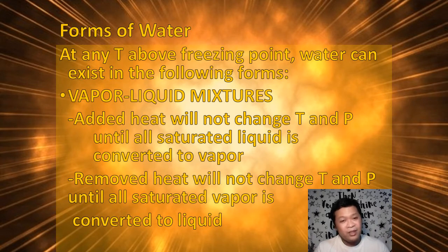So, dahil yung ibang lumang ref nag-on off lang, or yung iba naman, they run at let's say half the rated capacity, kaya kinukuha natin yung average na let's say over a day. Kasi yun naman ang mahalagang bottom line sa atin: how much are we spending for our electricity cost per day on this appliance para ma-multiply mo in a month, what percentage of my electricity bill ay dahil sa refrigerator na ito.